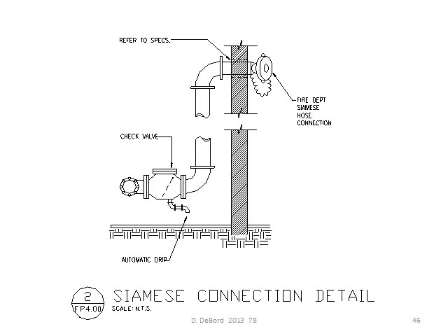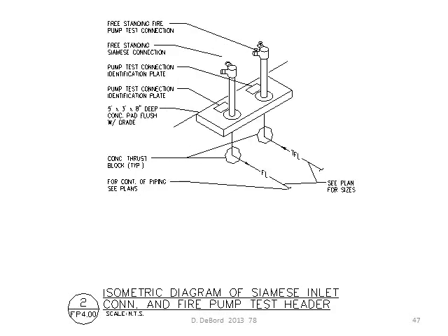If this is used in the winter, then the piping going down to the check valve could have water in it. You don't want that to freeze, so it has that ball drip valve to let the water out and not break the sprinklers.